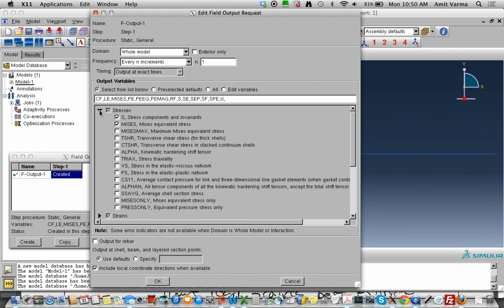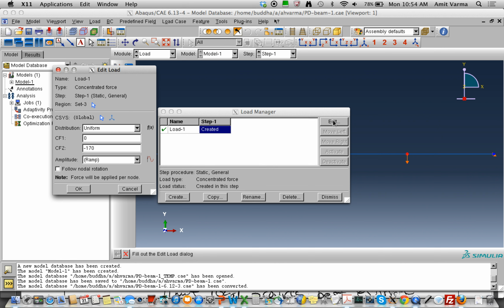I know that the capacity is 160 kips. I saw that when I did my hand analysis. So I applied a load of 170. I know it's never going to get there. It's going to get to 160 and crash and burn. Right? So what I'll get from this analysis response will be behavior that looks like this. It will go up here and it won't be able to propagate in this direction because it will never find equilibrium for 161 kips. It can't. The plastic load is 160 kips, after which it just becomes a mechanism and starts falling.